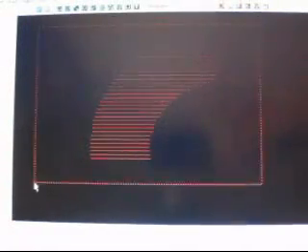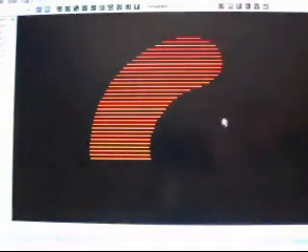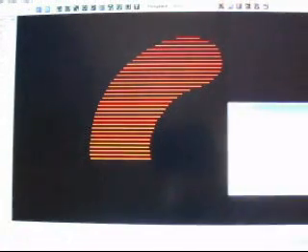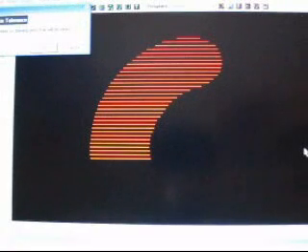All right. So basically, I'm going to select all of these, and I'm going to right-click and go Convert to Polylines. Now you see that took fairly quickly, and now I'm going to go Polylines Join. And you can join this at whatever tolerance you want.